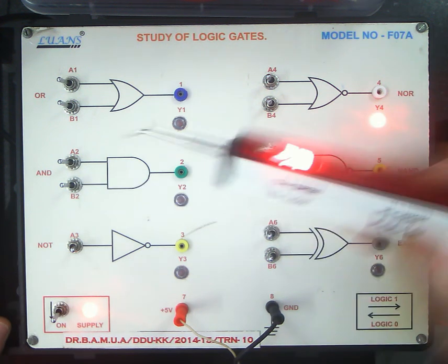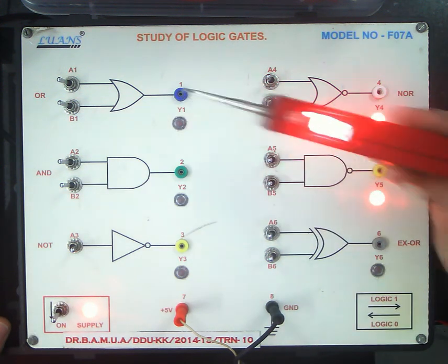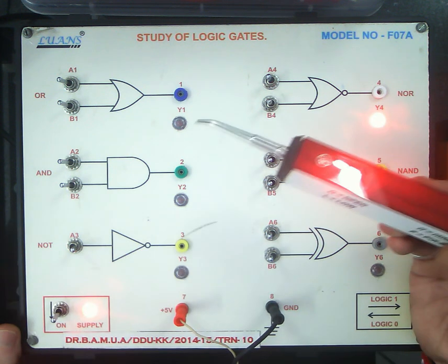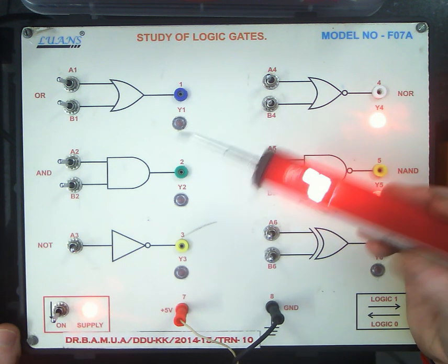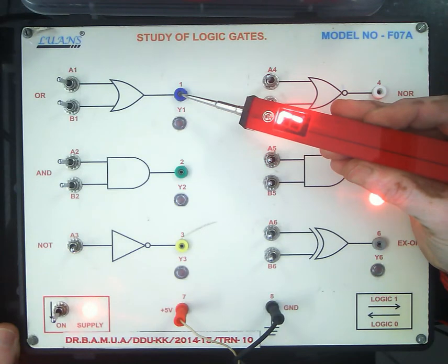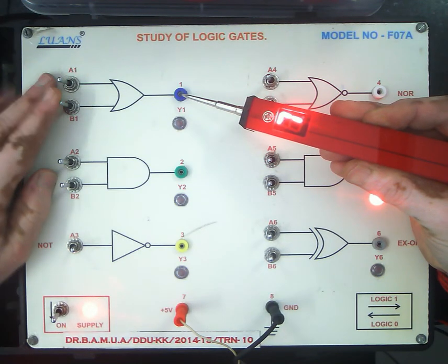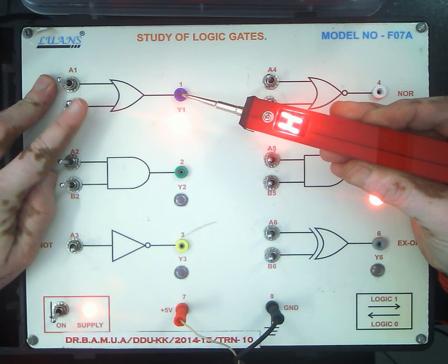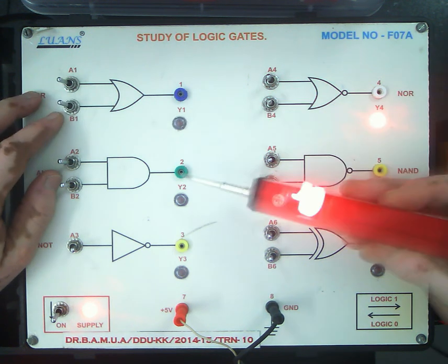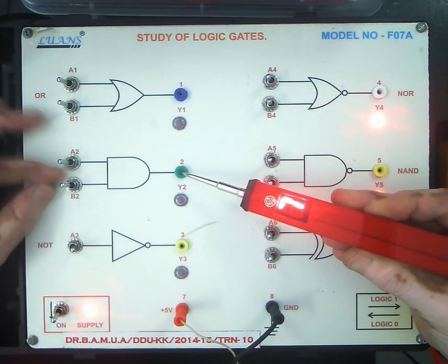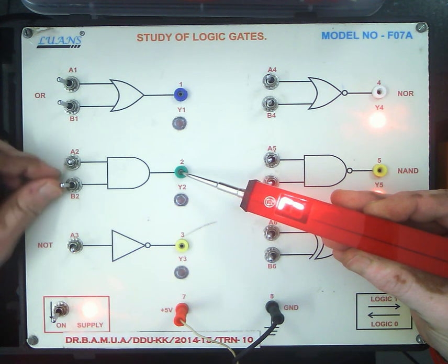So let us see now if this actually happens. It has a notch like this, so that you can connect it to the terminals of an IC. I will put it here. Now you can find it is low. I will make any of the inputs high, it becomes high. Okay, so this is a logic probe. I will put it in an AND gate configuration. You can find both the inputs are low, the LED is not glowing, so this is low. Both of them are high, it is H.